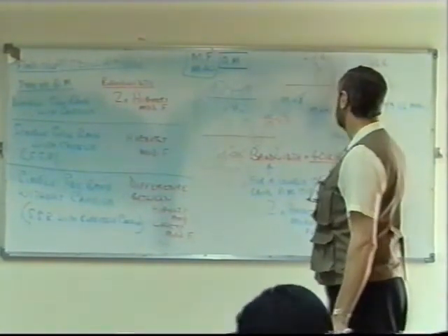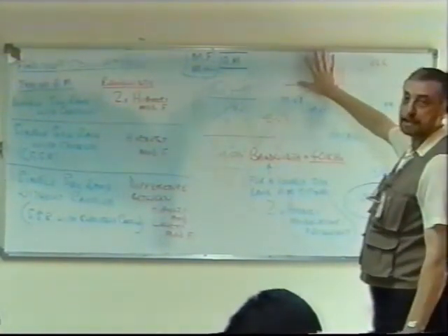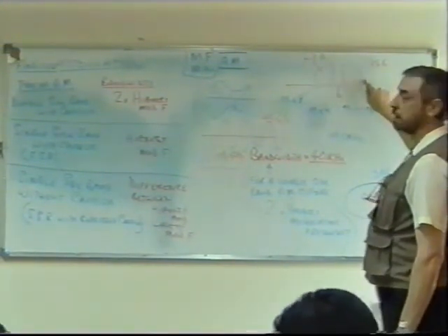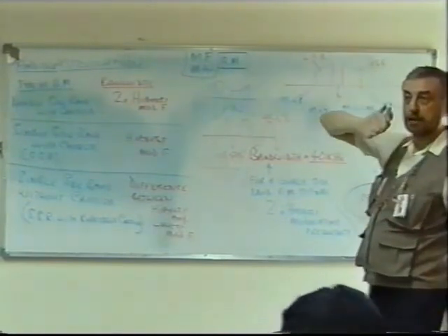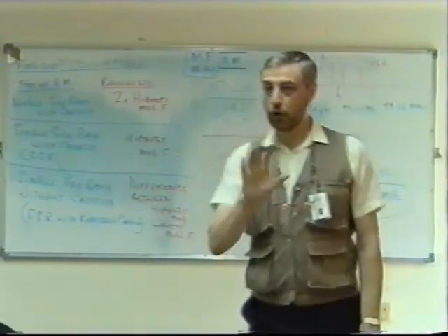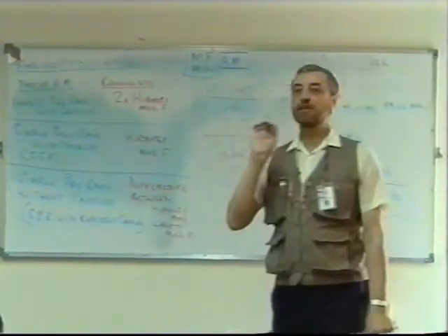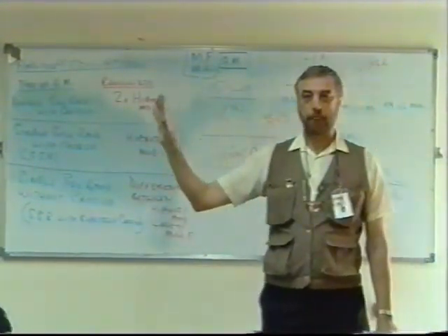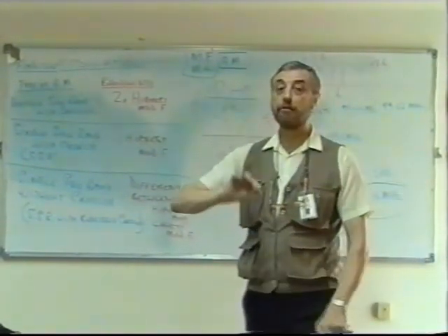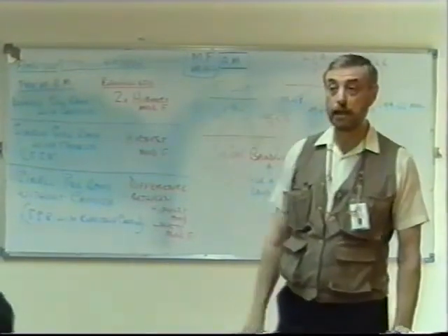I'm modulating that carrier with 20 kilohertz, and then I'm suppressing a sideband and the carrier. What do you think the output will be? Zero, exactly the point. No modulation, zero output. The transmitter literally transmits nothing. And the bigger the amplitude of your signal, the greater the output from your transmitter will be.